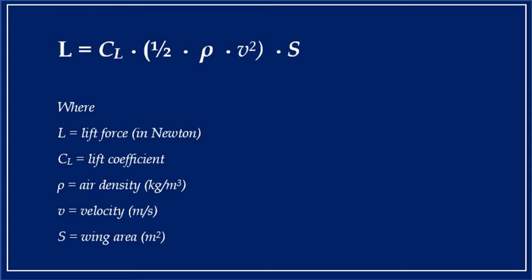When you are asked to calculate the lift of an airplane, usually the lift coefficient is given. The other way around, it can also be that the lift force is given and that you are asked to calculate the lift coefficient, in which case you can rearrange the equation to calculate the relevant lift coefficient. If you don't know the lift coefficient or the lift force, what you can always do is go to airfoiltools.com, the link is in the description, and look up the relevant airfoil for your particular aircraft. Now, let's use this lift equation in a relevant example.